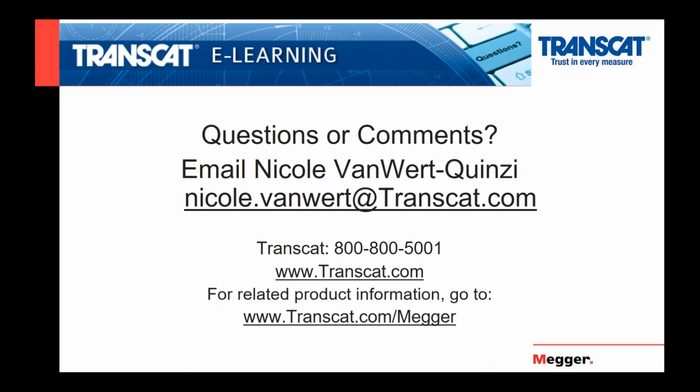So there's two classes in the standards, Class A and Class S. And Class S is not held to as high a standard as Class A, and should only be used for statistical purposes such as surveys and troubleshooting. And they usually have a limited subset of parameters as well. So with the demand for PQ analyzers increasing, folks buying them should be aware whether they need Class A or Class S. It's very important not to get a Class S when Class A is required.